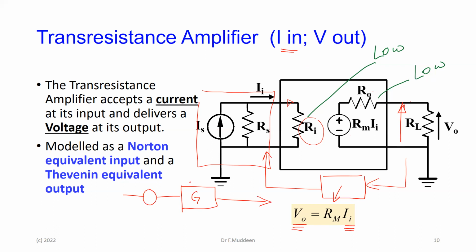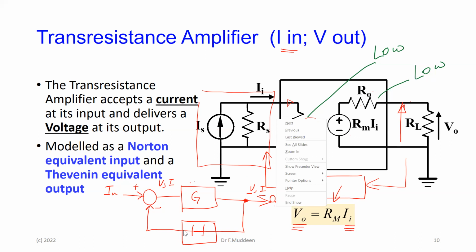This is either the voltage, the current, the transimpedance, or the transconductance amplifier here. So I'm now going to have to take something on the output and supply it back to the input, negative feedback, right? So input here, output. If I'm taking it here, I have a little transfer function, my feedback network. Remember, the input could be voltage or current, the output could be voltage or current, and we saw the four combinations. So when I'm feeding it back now, I can sense either voltage or current at the output, and I can feed back either voltage or current depending on what the input is.